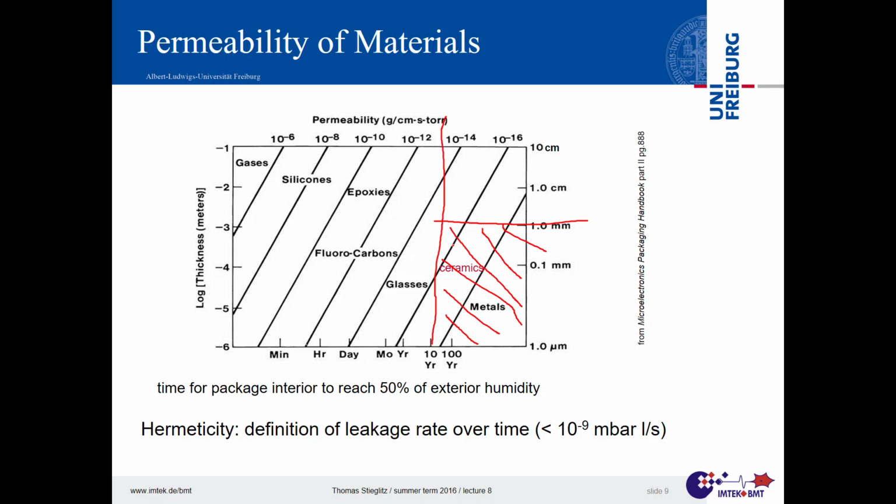And that will mean you have to measure a certain time. There are international standards, and if you go below 1 centimeter cubed of the package volume, you come into that particular standard that is binding in the US. It's a military standard, with funny things like you have to place your device first for 30 days into an environment with helium, so that the helium can creep in if there are some holes in there. And then you have to measure for 10 or 12 days if the helium comes out.